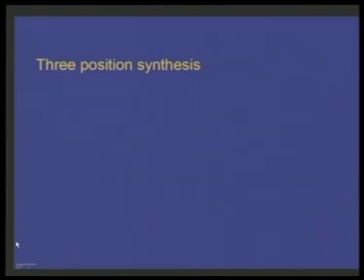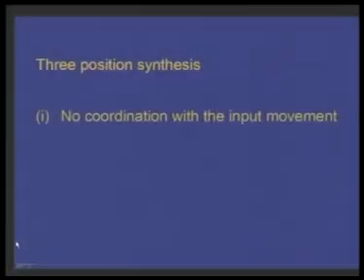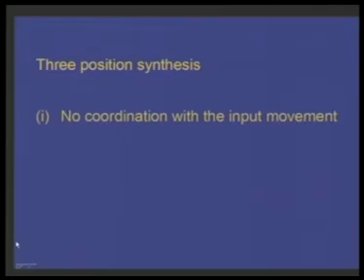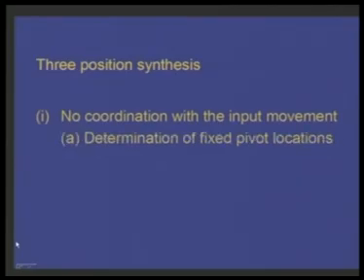After solving this problem, we get into three-position synthesis. That means the coupler has to occupy three specified configurations, namely 1, 2 and 3. Here, of course, we will discuss without any coordination with the input movement. That means we are happy so long the coupler passes through these three positions, and we are not bothered about what is the corresponding movement of the input link. Under this heading of three-position synthesis without coordination with the input movement, we can classify the problem into two headings.